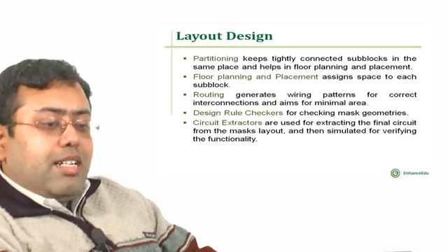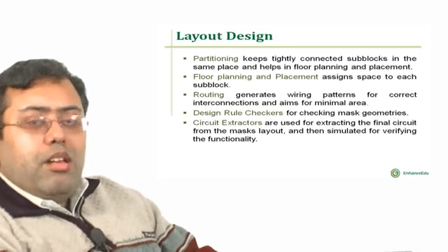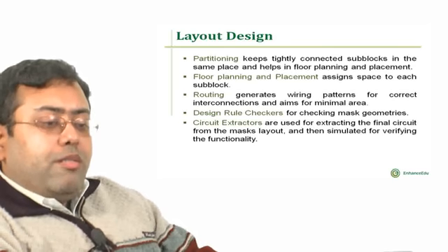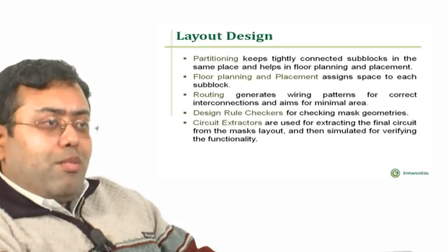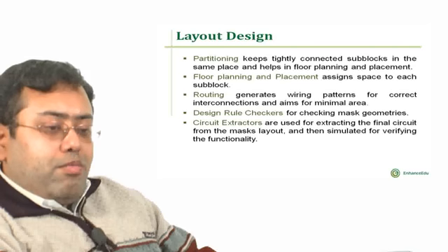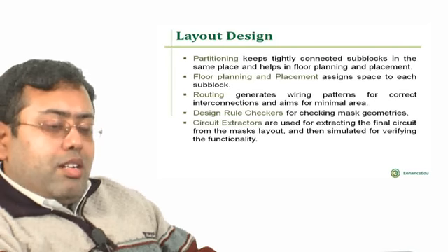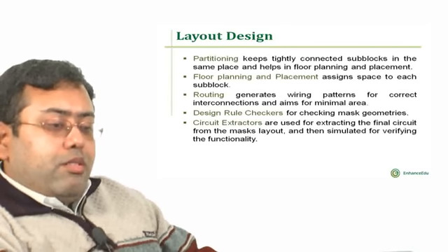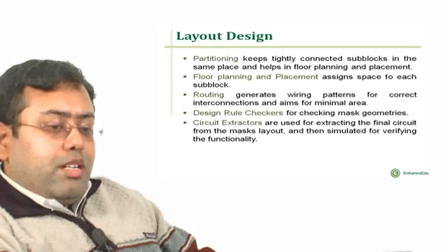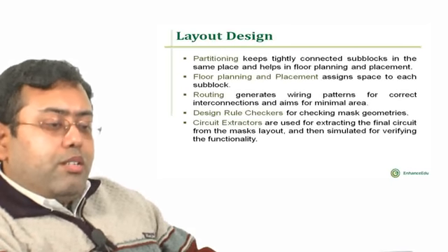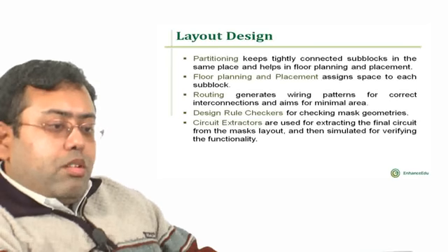Partitioning keeps tightly connected subblocks in the same place and helps in floor planning and placement, where you choose a large problem and decompose it into sub problems of manageable size, so that they are implementable using the limited memory and limited speed of the processor.